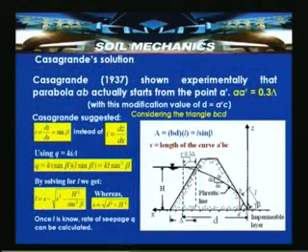So by knowing S, we can now estimate L. By knowing L, we can estimate Q is equal to KL sin square beta. That is, L is known and beta is the angle shown here, which is the slope inclination beta. So once L is known, the rate of seepage Q can be calculated.